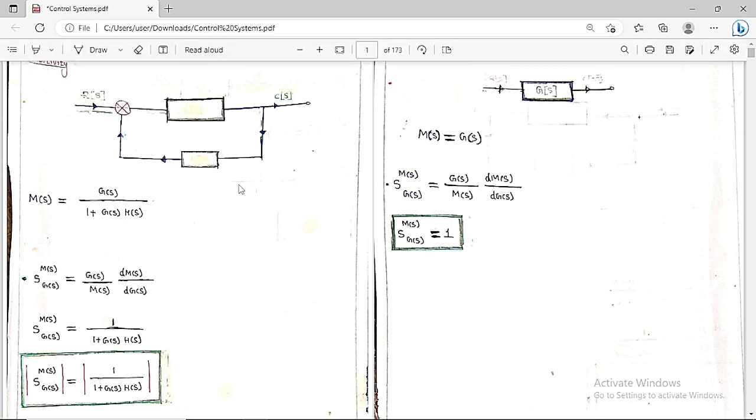By default, here we are always going to choose the negative feedback system. This is a negative feedback system, and this is positive and this is negative. This is called G of S. G of S is called the plant transfer function, whereas H of S is called the feedback transfer function. There is a negative feedback from output to input, and the feedback transfer function is H of S, and this is the forward path, because the plant transfer function is G of S. So this is a basic block diagram in the case of the control system.